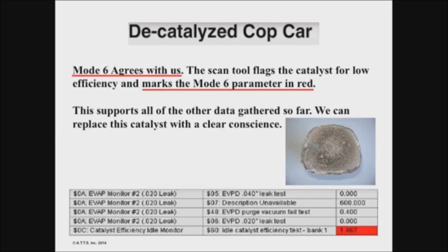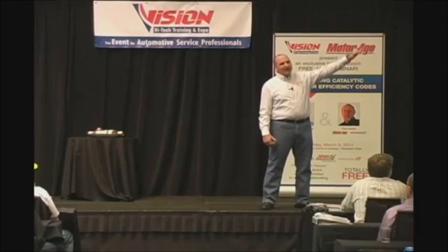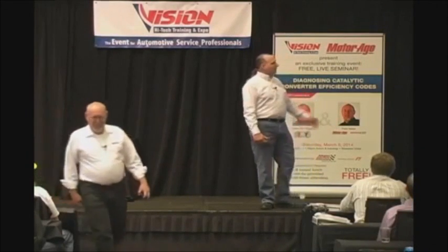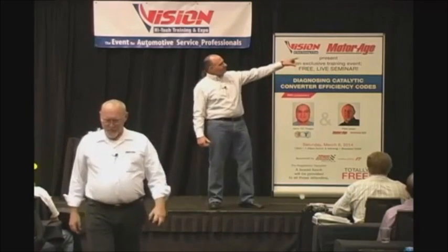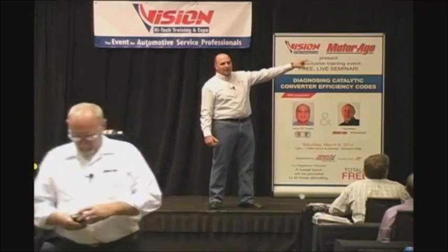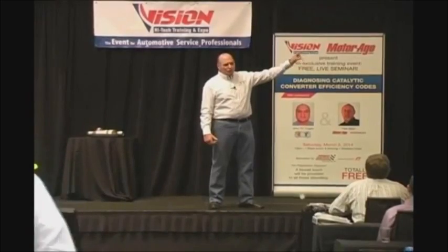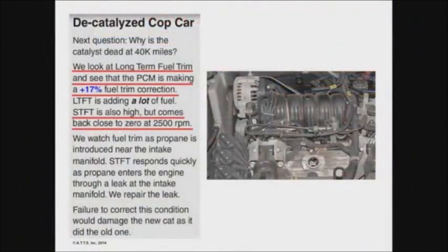Okay, so now these motors have a lot of different problems, don't they? We know there's gasket leaks, there's hose leaks in the back, vacuum boosters sometimes go. I mean, a fleet of police cars that I worked on, the PCV valve that's near the alternator there, how many people put the wrong PCV valve in? The wrong flow is going to let your fuel trim go, or they leave the O-ring off, it's going to go bye-bye. In this case, one of the things we looked at is fuel trim on this car is a plus 17. Okay? Now, that is a biggie. Now, that's long-term fuel trim.